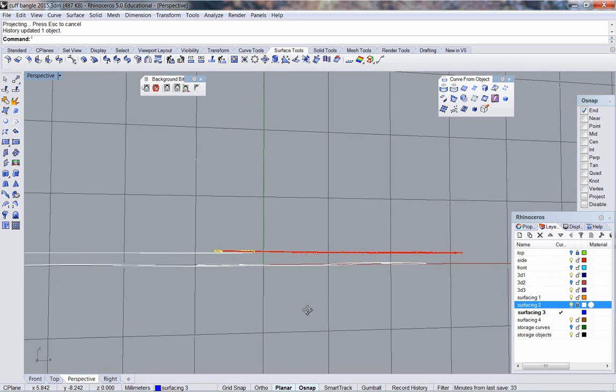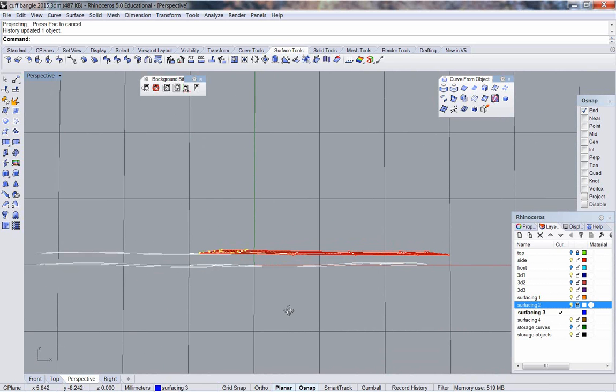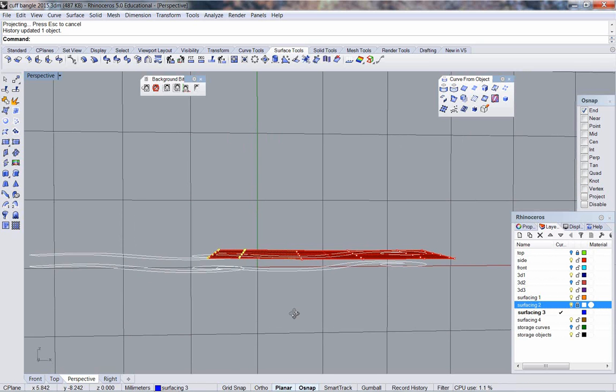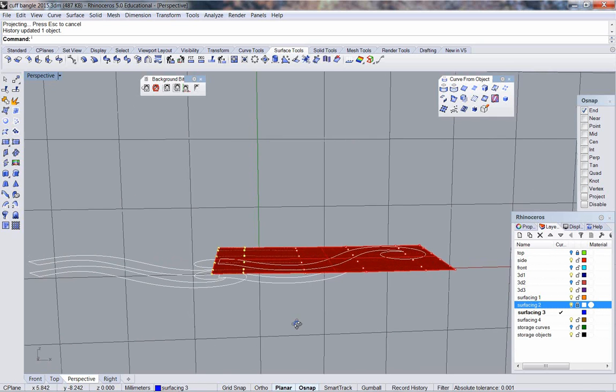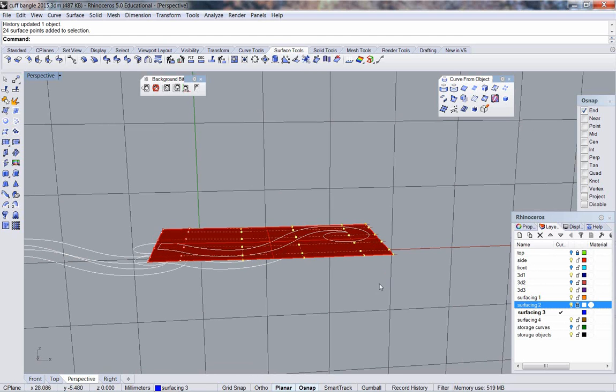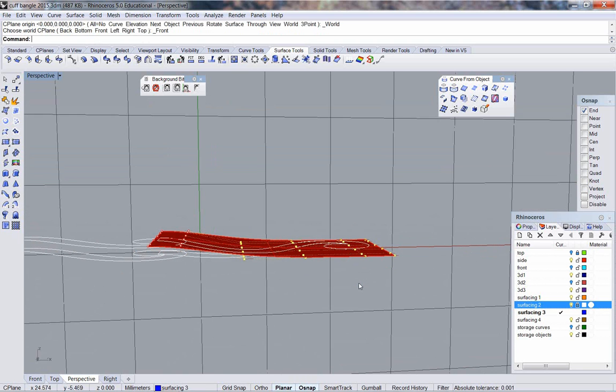Well, that's interesting. It was already under 2 millimeters. That is interesting. Well, since that's the thinnest I really want to go, the rest has to go higher, and I would like to know how much higher it's going to go. So I'll do the same thing. Project to C-plane, that's C-enter on our shortcuts. Y. Front C-plane, M-enter. Move from, click anywhere. And I'm going to take that up to 4 millimeters for starters.